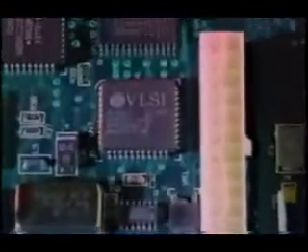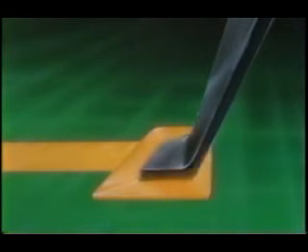As the signal travels from one chip to another, it encounters increased capacitance in the large surface areas of the pads, the solder, and the metal leg of the packaging. The most difficult are the thin wire bonds, which resist the flow of current.